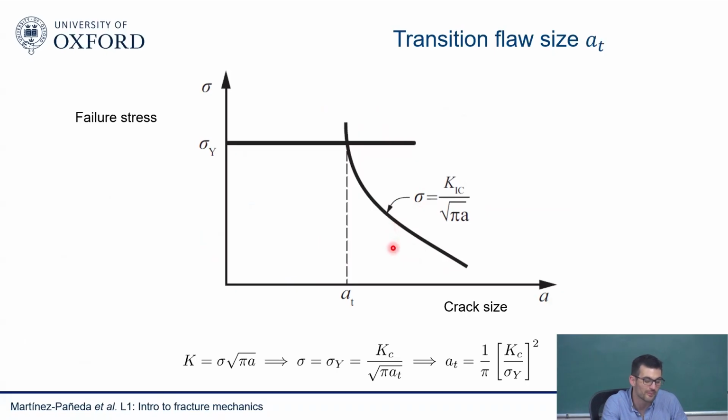However, sometimes in engineering practice, you don't have full control over the loads. Imagine you're designing an aircraft. We know what is the typical crack size, the typical defect that we can inspect in those components of your aircraft. And it's going to be subjected to an inside pressure of your plane. So you're going to be working somewhere here, and you know what material to use, you know the pressure because you know fracture mechanics. But it could be that there's an increase in pressure that you didn't predict. So if you're somewhere here, maybe catastrophic failure will happen.